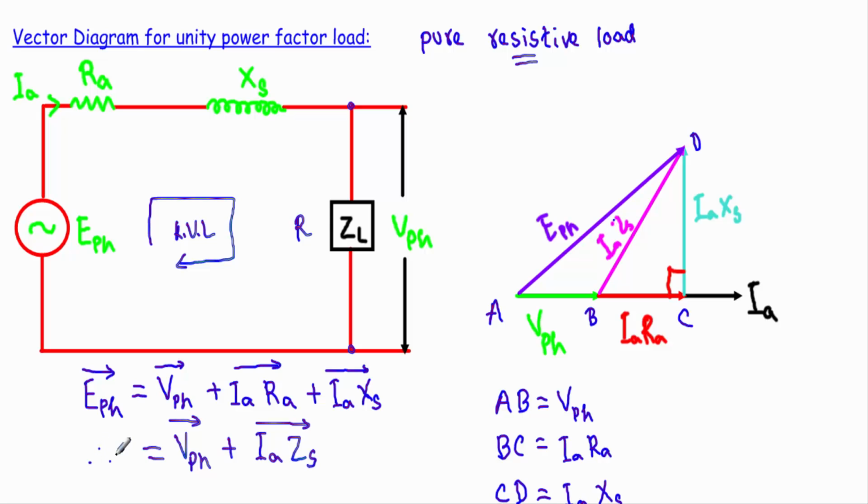So I can write EPH equal to VPH plus IAZS. Now I will draw the vector diagram, and after that I will show you the relationship between this EPH or no load voltage EPH and the full load voltage VPH here. Okay,